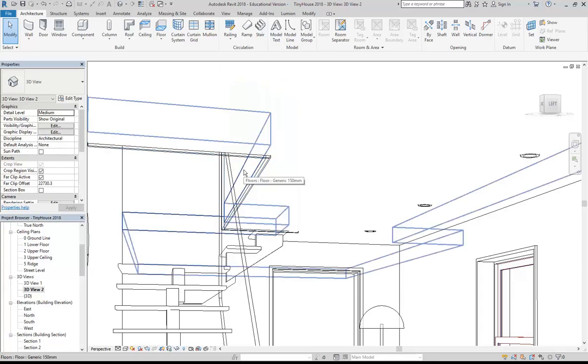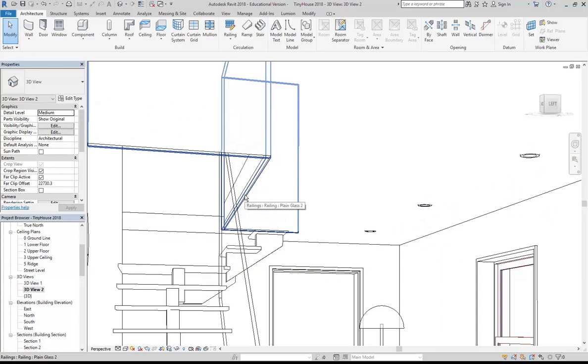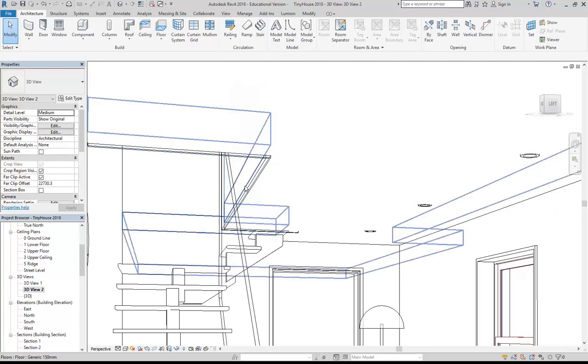Otherwise, do you know what you'd need to do if you do need to cover up that edge? Pretty much, yep. So in real life, you'd always have to cover up the edge of your floor. And it's actually called a fascia. So it's a floor fascia, and that's an important thing that you need to know about. But as I was saying before, you don't always need to model it.